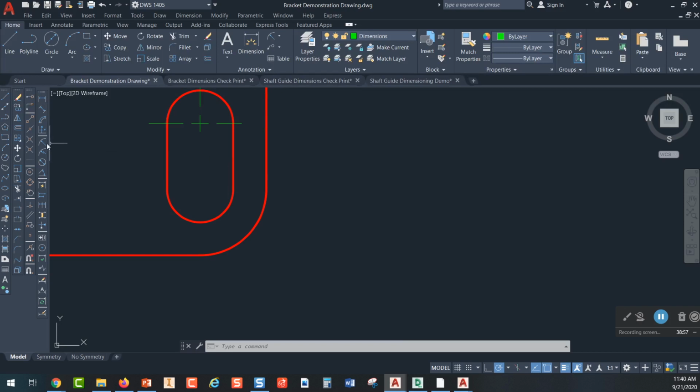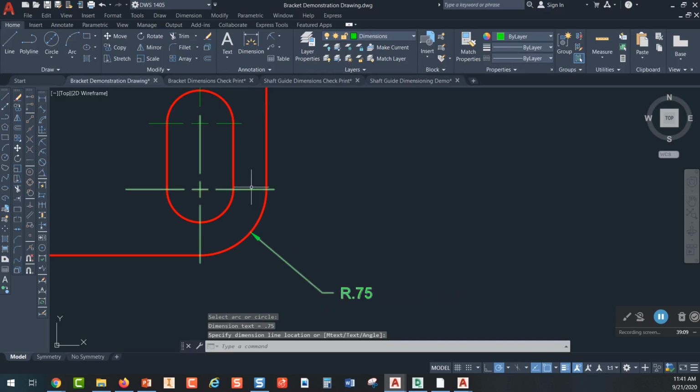So instead, what I would do is come pick on the radius tool, pick right there on that arc, which we drew as a fillet, and look at that, AutoCAD automatically drew that. Now, the problem with it is that it also added those, and it drew up and it took out that gap that I want to have right there.